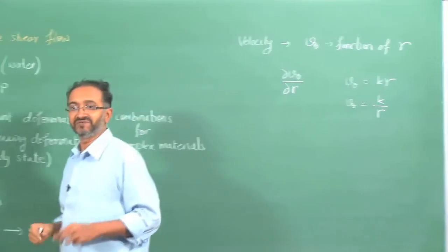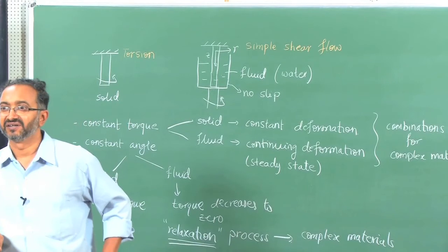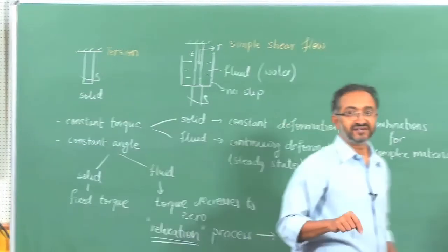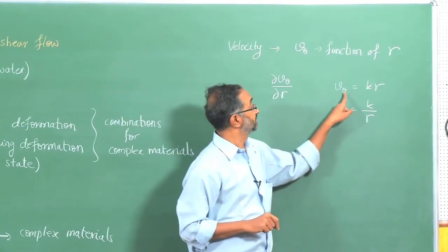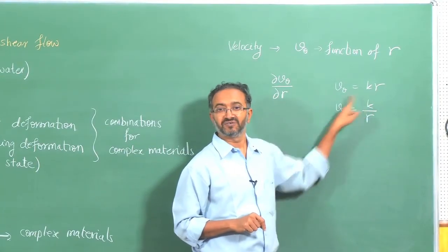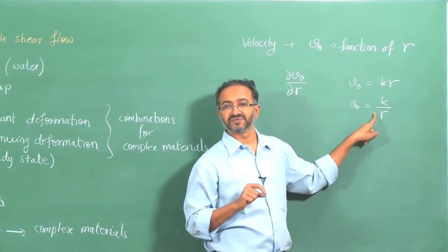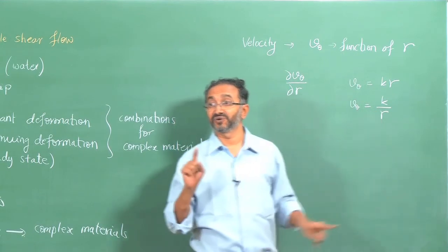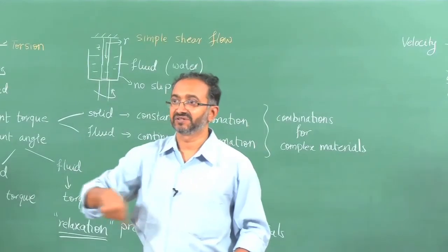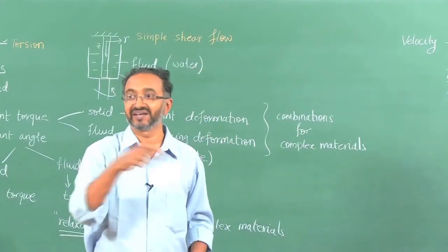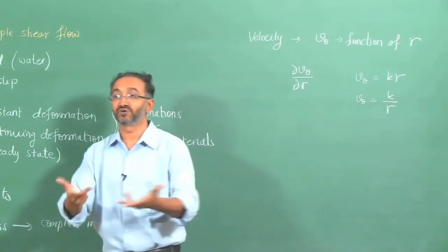Both of these are tangential flows, with velocity only in the theta direction, but if you work with these two examples you can see that this is a rigid body rotation while this is an irrotational flow, for which there is no local rotation. A combination of these two, the forced and free vortex, is a good model for a vortex.